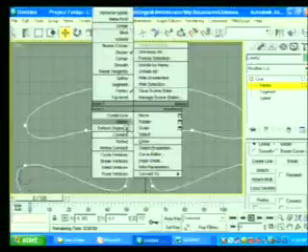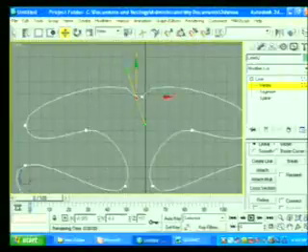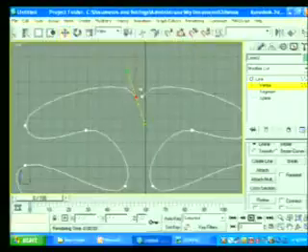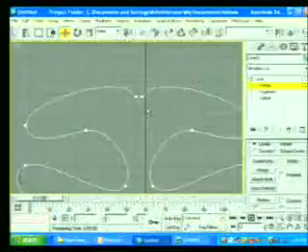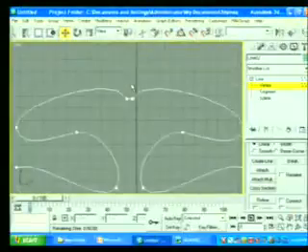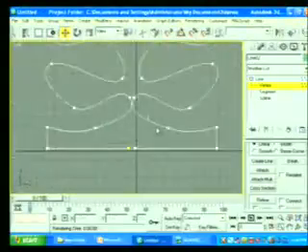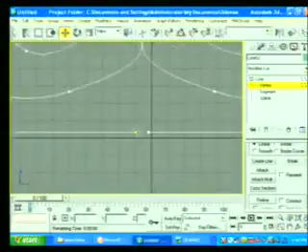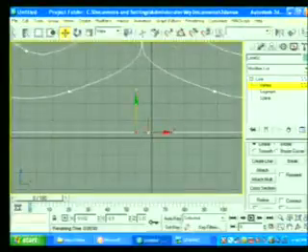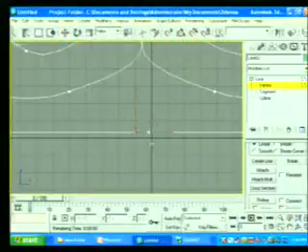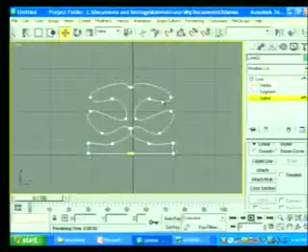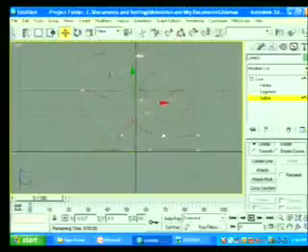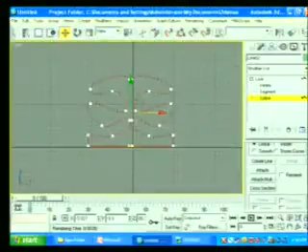Go to the vertex, select the vertex and right click on the vertex, and here we have an option of connect. Right click on the vertex, say connect, drag this and drop it to the vertex to be connected, right click, and it is connected. Select the vertex, right click and connect. If I select the segment, it is one mesh or one shape.